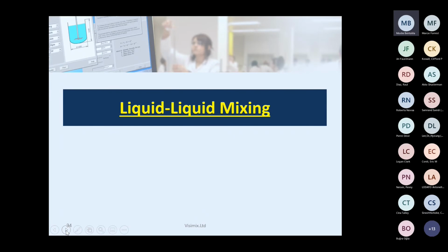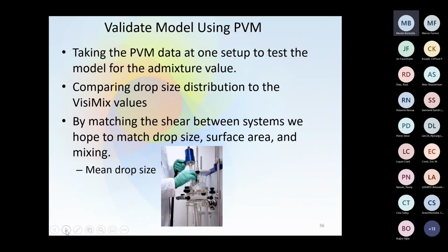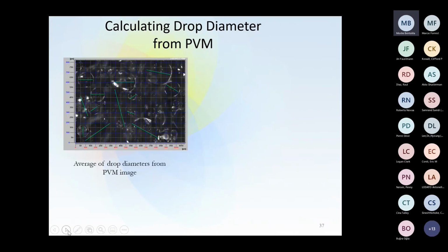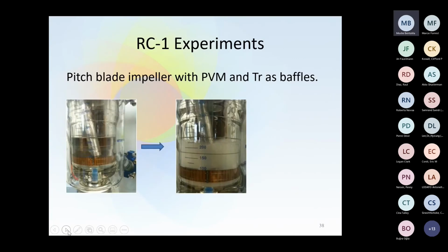Okay, for liquid-liquid mixing, a company in Dallas did a very good job about it. They add some process and they need to have two phase drops into the liquid phase, into the oil phase. And what they did, of course, they measure the drop size again and again, and they try to generate the same forces from rotor stator in a big equipment for the laboratory one.